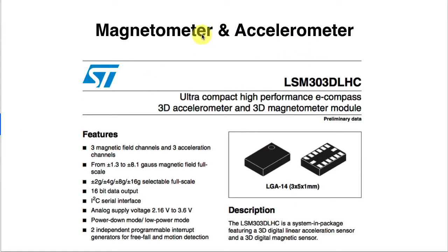If we add to that a magnetometer, often built into the same package as an accelerometer, then we've got multiple sense elements that'll tell us which direction we're facing, which direction is down, and give us full position orientation. This can be really useful if you're trying to line something up and maintain its alignment.